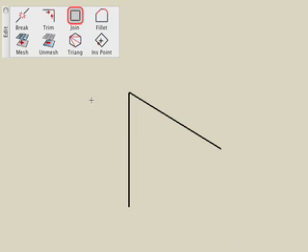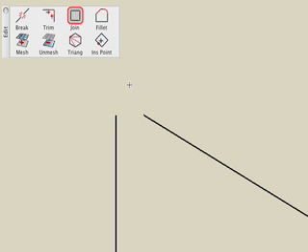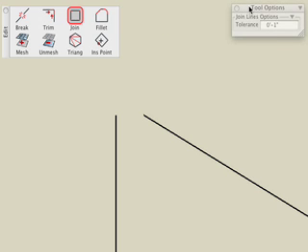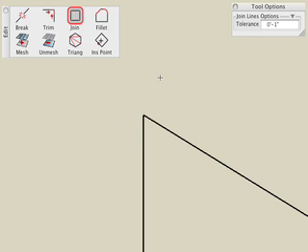What if I try to join two lines together and their ends are not touching? For example, if these two vector lines, I'll zoom in really close and you can see that there's a gap there. Well, the Join tool does have one option. If you look in the Tool Options palette, you see that there's a tolerance setting. If I try to join these two lines, as long as that gap is within the tolerance that I have set, it'll actually still join those lines together.